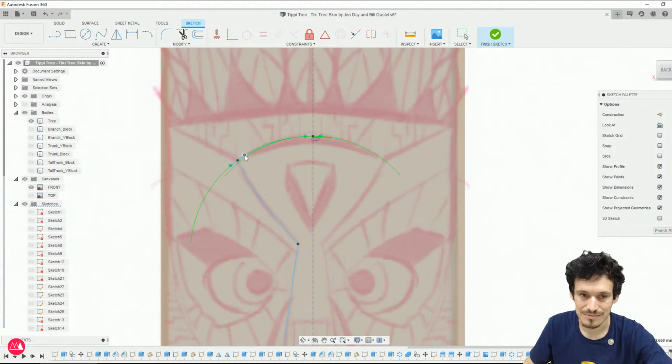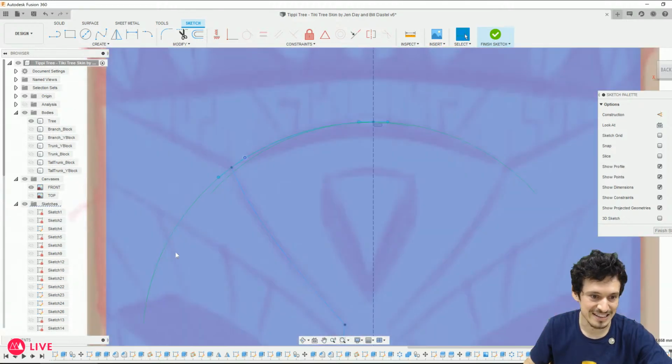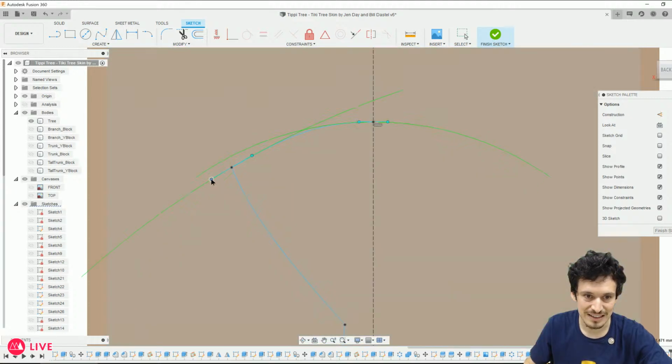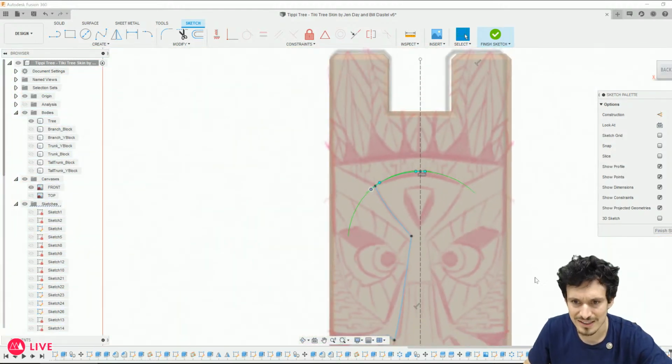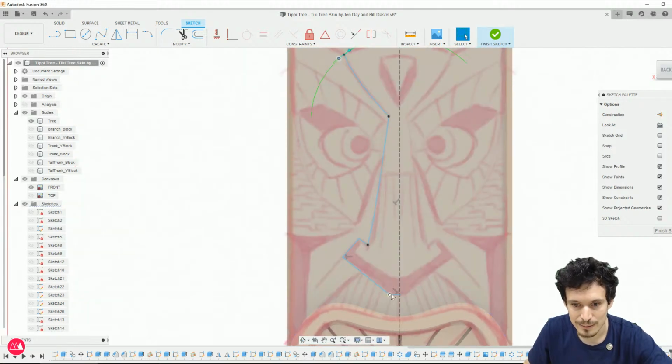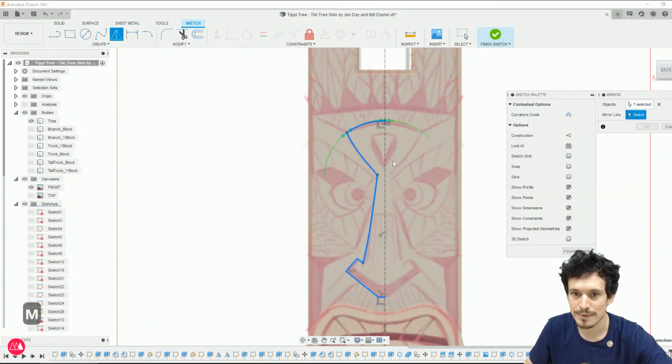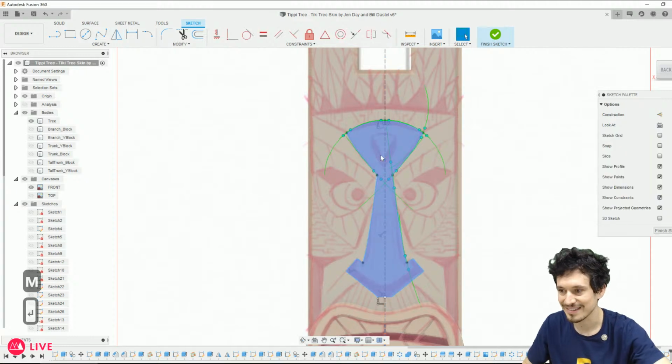All right. Another thing about the spline, you might notice these green curves coming off. By aligning these curves, it'll help you create really smooth splines. See, I can just adjust this until those two almost come together like that. Boom. And that basically makes the smoothest curve possible. Let's stick with that smooth curve. Now we'll select this line. We can select the whole thing by double clicking. Shift M and mirror it.